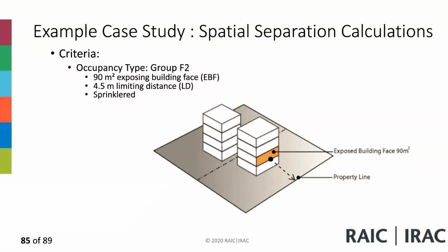18%. So for 4.5 meters, I use the 4 and 100 square meters. Exactly. Because it's between 80 and 100, you have to go to the 100. So you go more conservative, right? So you've got 100 square meters, and then for 4.5 between 18 and 26, you told me it's 18.